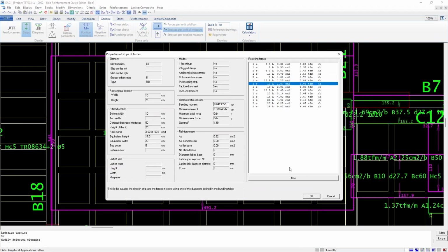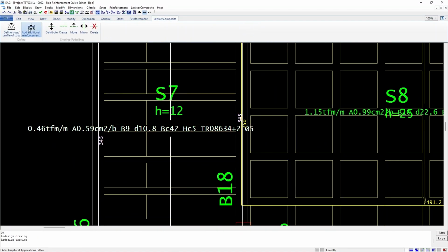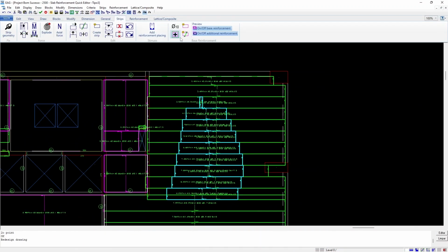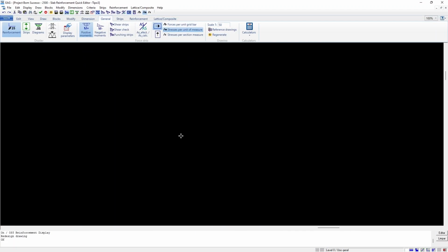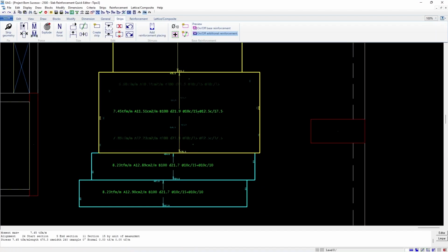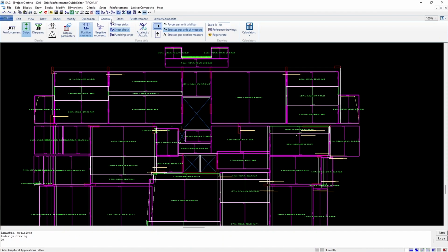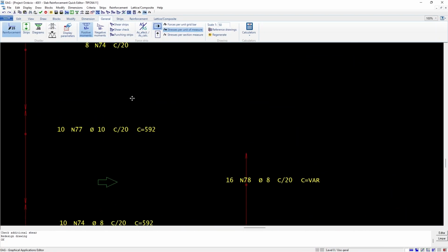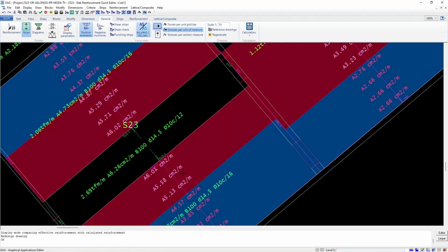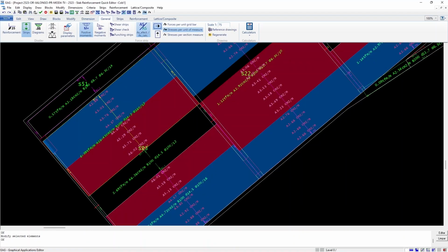Bar diameters and quantities are automatically selected for each force strip. In the case of lattice slabs, joist selection and additional reinforcement detailing also occurs through an automatic process. A scheme with base and complementary reinforcement can be adopted to generate a more economical distribution. Bar anchorage of the longitudinal bars is calculated automatically. The editor also graphically indicates the differences between provided and required reinforcement, helping to identify over or under reinforced areas.